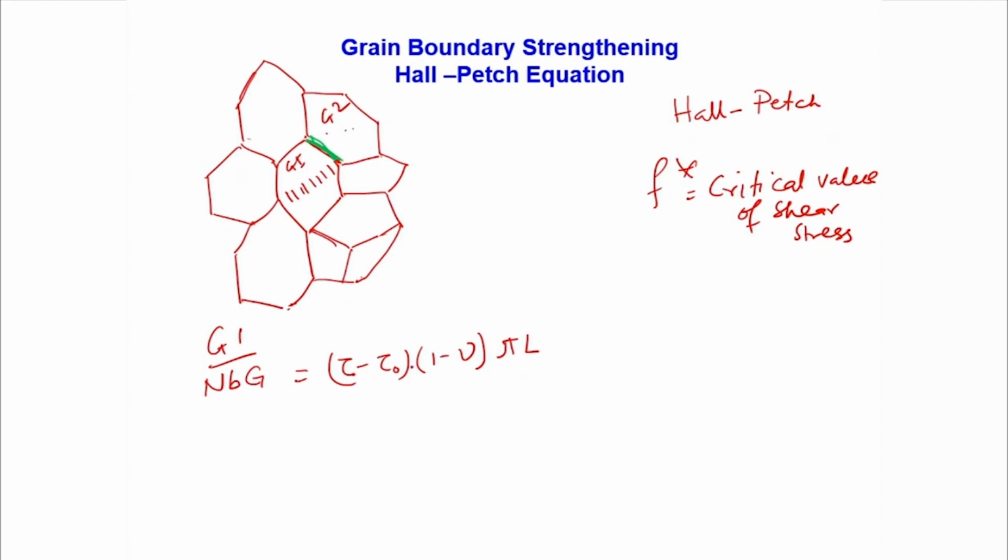So then what is tau minus tau 0? Let us explain. Tau 0 is the value of the shear stress which is used for other strengthening mechanisms. There will be other strengthening mechanisms, like solution strengthening, precipitation strengthening, dispersion strengthening, many other things, correct. Or there will be strengthening because of aspects of Suzuki locking, many other things.